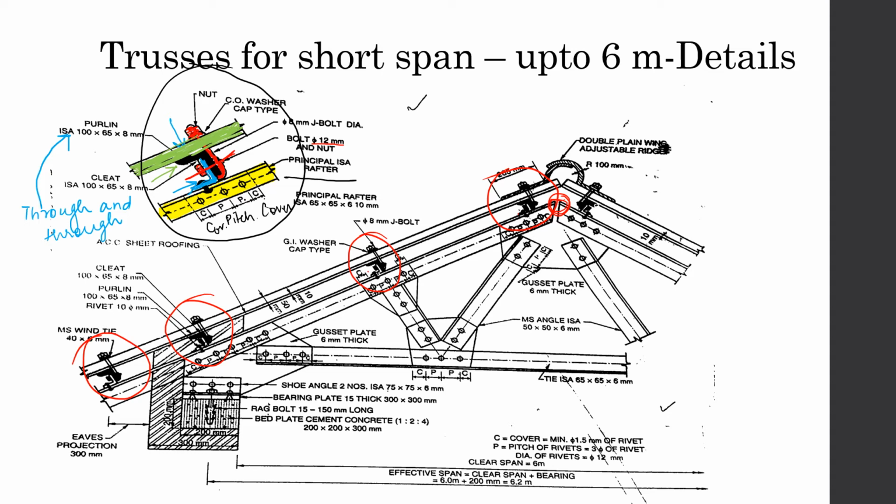So this whole area which I circled right now is prone to let water in if rains appear. To cover this point which has been highlighted with the red, we provide a ridge covering.